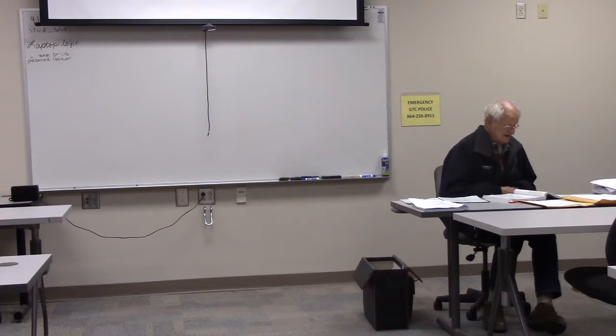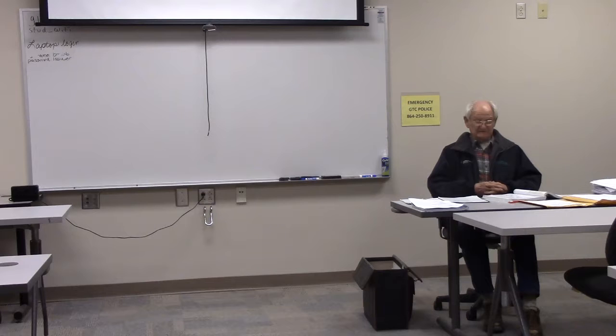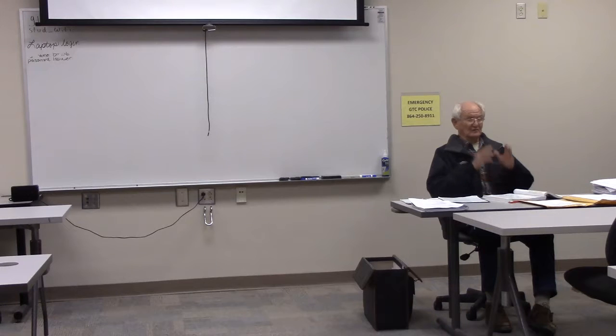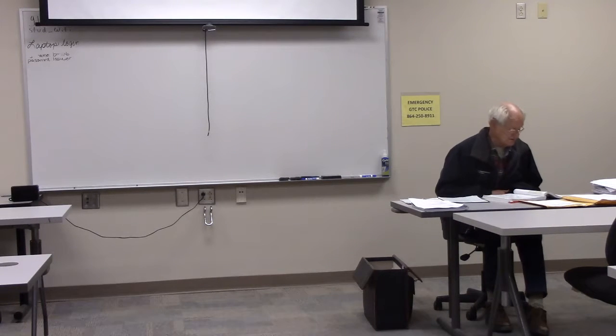And then size in outlet boxes. Now this is something you need to pay close attention to, because there's going to be some questions concerning things that take up space in a box, and how much space they take, how many wires they eliminate from the normal count of wires that can be allowed there.